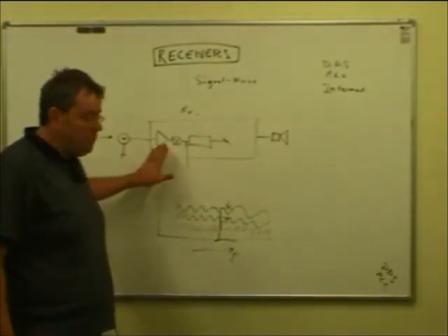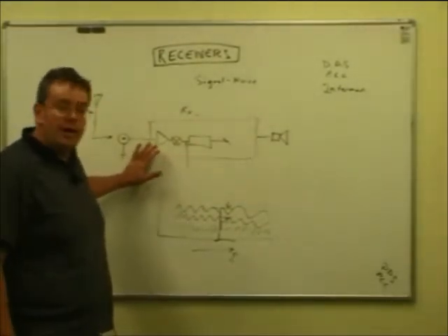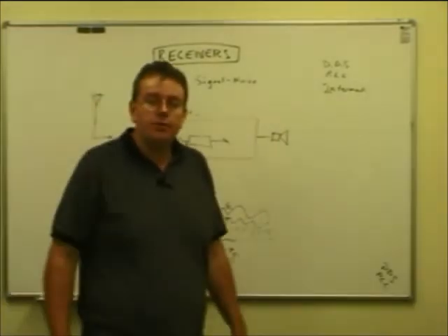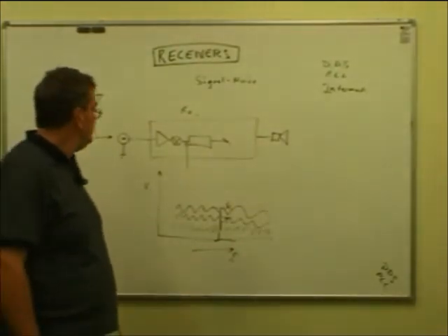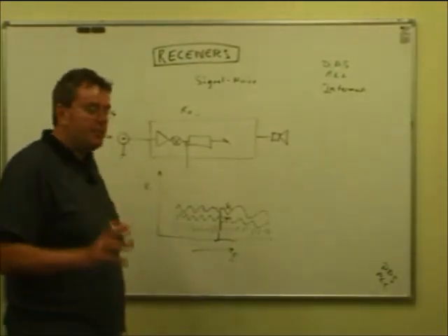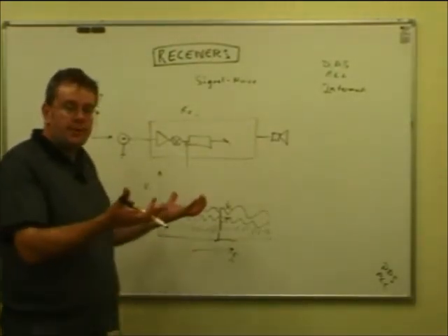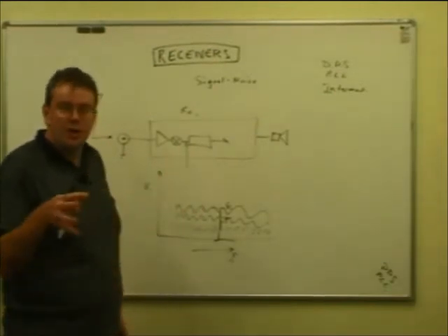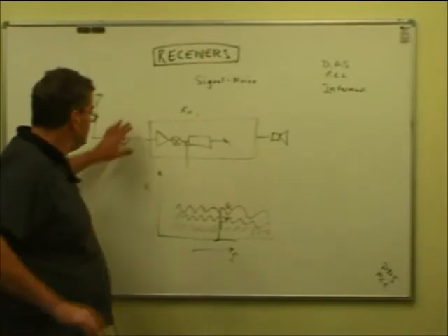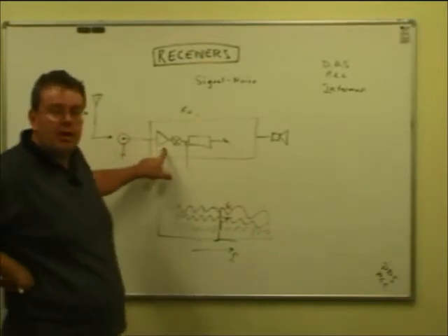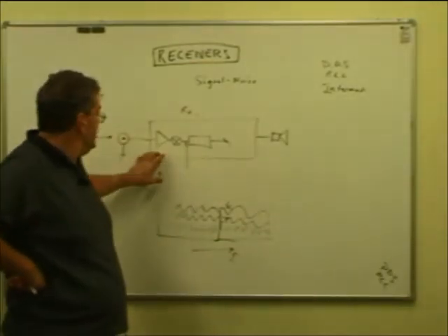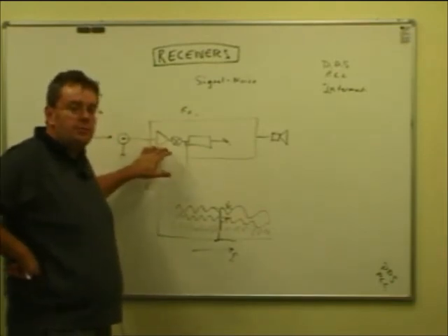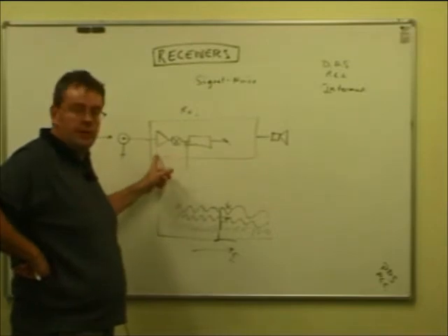Receivers generally have the radio frequency amplifier at the start as the lowest noise amplifier in the receiver, to lift the signal up a bit, just to get it started as it heads through the receiver. It's an oversimplification, but it's good enough for this. But that has to be made relatively low noise, because this amplifier is dealing with a signal at the weakest it'll ever be.